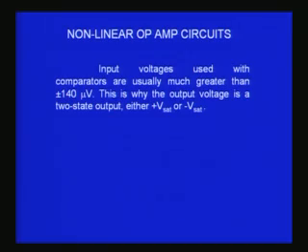So, the output transition happens within plus or minus 140 microvolt at the input, total 280. Over 280 microvolts it will make a transition from minus to plus or plus to minus, and therefore that helps us to detect the difference in voltage when I compare two voltages within plus or minus 140 microvolts.